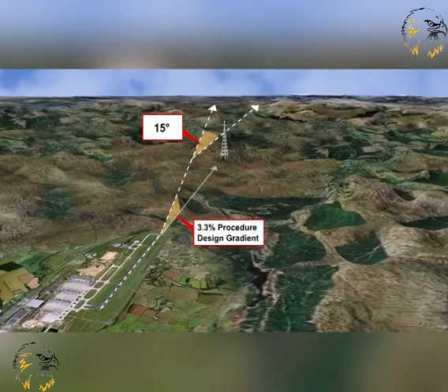Departure procedures will be established for each runway to be used, and will define the procedures to be used for each category of aeroplane based upon an all-engines running procedure design gradient, PDG, of 3.3%, to achieve minimum obstacle clearance. This procedure will assume that pilots will not compensate for wind effects if using radar-vectored departures, but will account for wind if on a departure route that is expressed as a track to be made good. Unless radar vectors are specified, pilots should assume they must take the wind into account to follow the track prescribed in the procedure.